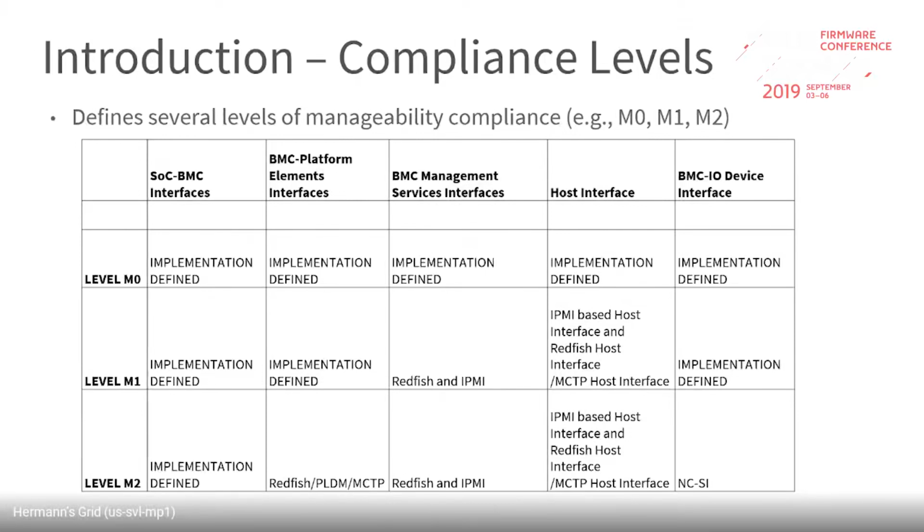So currently we are at level M0. I mean, our ecosystem, our partners are at level M0. It's all implementation defined. With level M1, we want to go with the BMC management services interface. That is the interface to the BMC. We plan to support both Redfish as well as IPMI. The host interface itself should be IPMI-based SSIF and Redfish host interface.